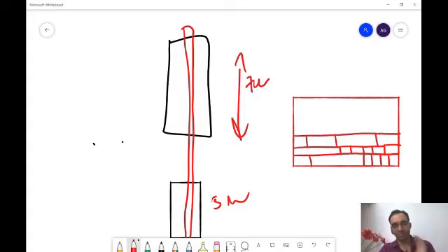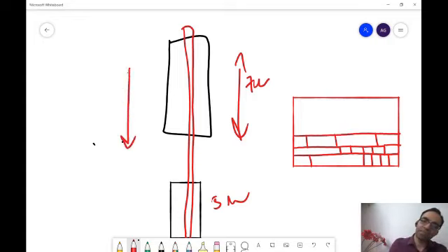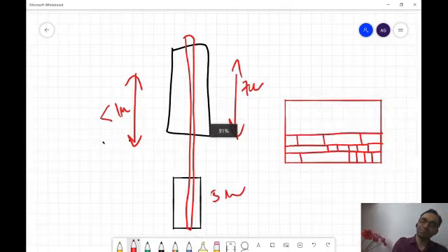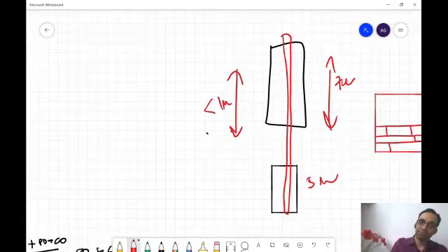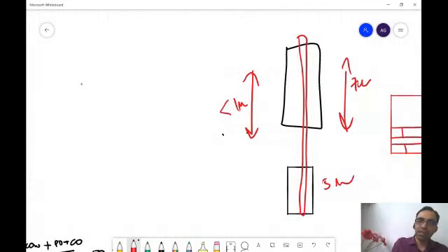Are you meaning the thickness of the gate oxide and the... No. I am saying this vertical extent should be less than 1 micron. But my effective PMOS should be 7 microns wide. So this extension is itself the width, right? Cascade them, sir. Like place them one by one vertically, 1 micron, 1 micron, 1 micron, 7 times and connect them. So what I can do is I will say that.